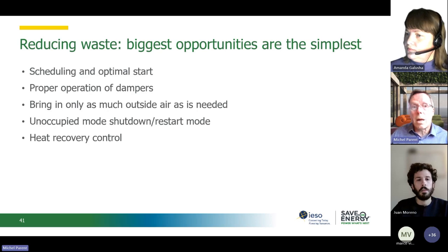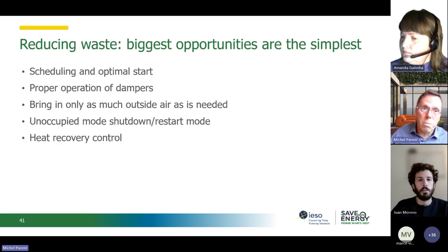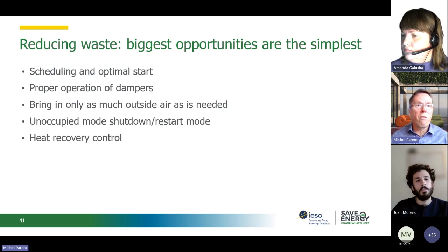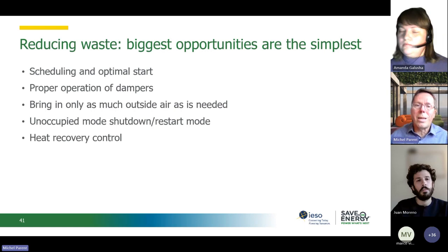If your outside air is driven by exhaust, and you're throttling down your dampers to 5%, I'm sorry, but you're not saving because your exhaust is driving the outside air. And that means now the outside air is coming from the door, from the cracks. You're depressurizing your building. You are better off bringing that air through your air handling unit. It will be filtered, it will be conditioned. And maybe then, like I said, you can say, hey, do I need all that exhaust?